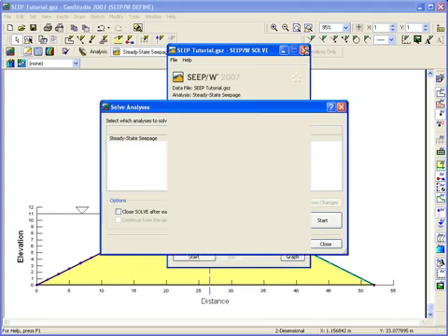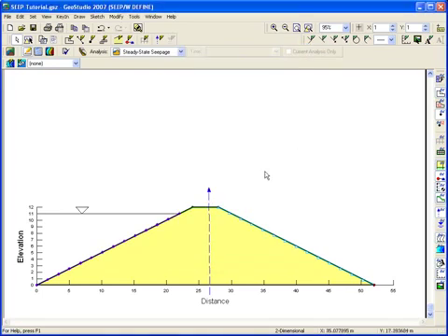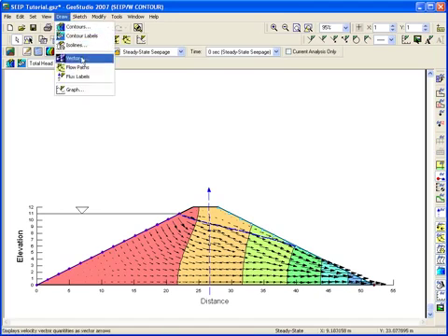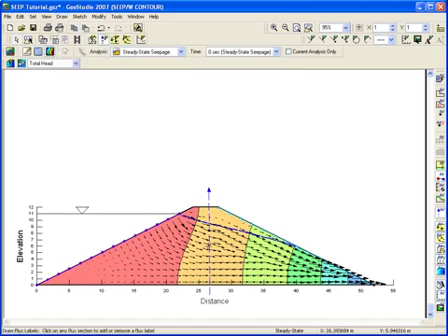You can view the results directly by clicking on the contour icon in the Analysis toolbar. By default, the contour results will include velocity vectors, the location of the zero pressure contour, and total head contours. The flux section results can be viewed by selecting flux labels from the Draw menu. Clicking on the flux section will make the total flux value appear. This value is the total amount of flow past the flux section per unit depth.